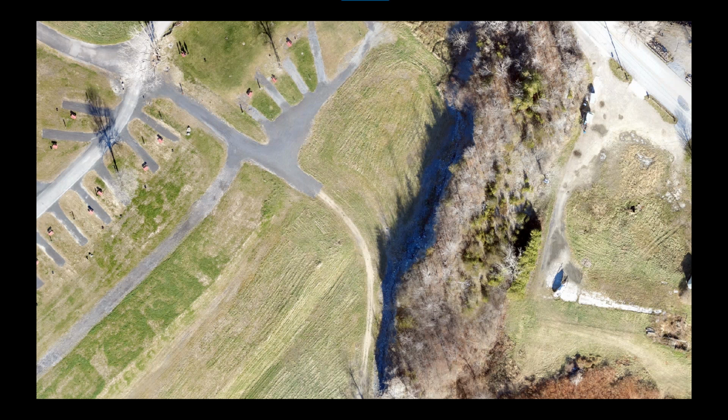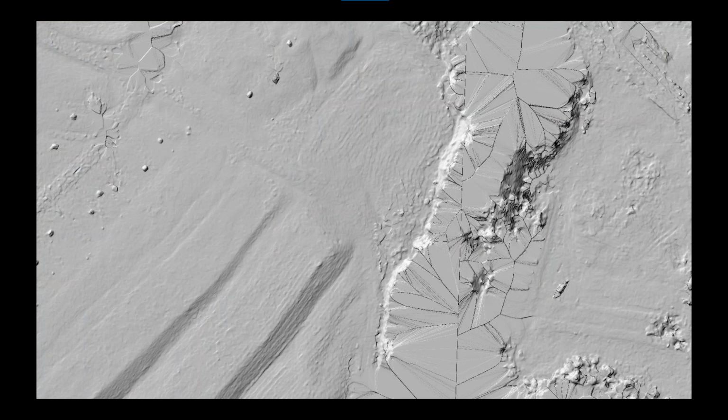That's the orthophoto. This is the digital surface model that was generated in preparation for building that orthophoto. When we orthorectify the images, we use a terrain model that's generated from the overlapping photos to do that. And what you see here is the data loss that's occurred over that area. Okay, so accuracy is going to suffer over that area in the orthophoto because we can see that it wasn't able to match points between the photos due to the shadowing in the terrain, and also any elevation measurements we hope to make from our point cloud aren't going to be very good.